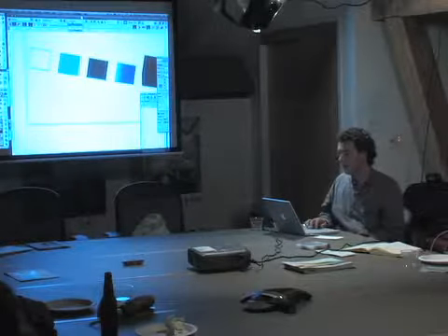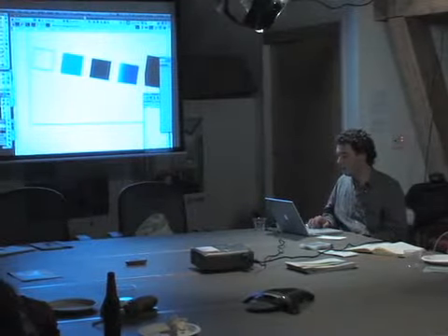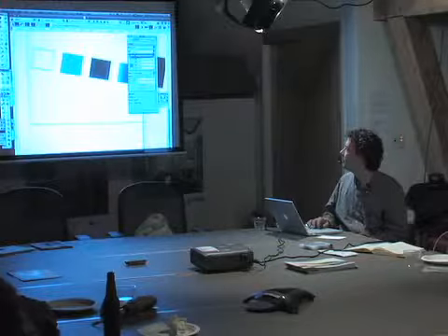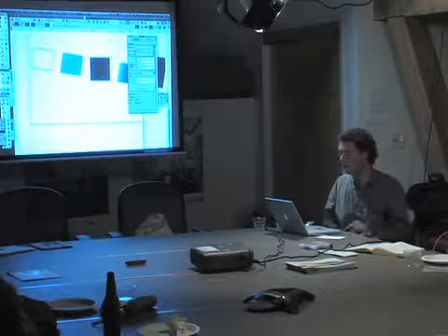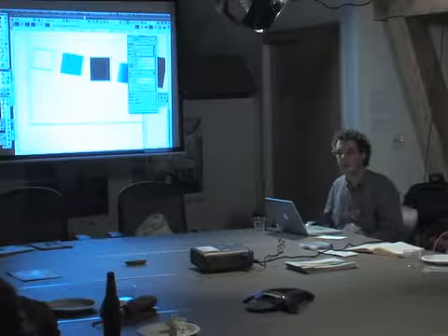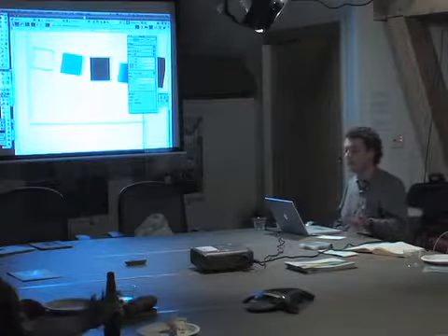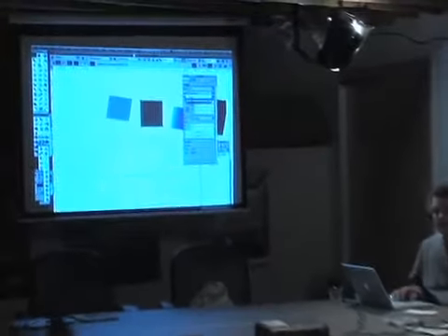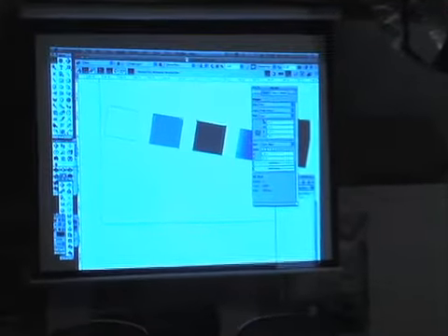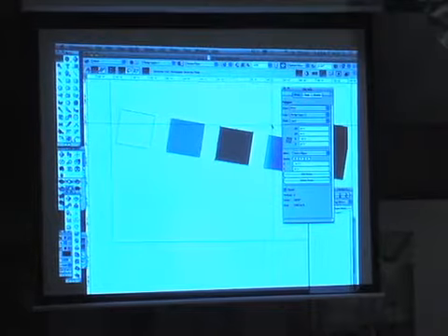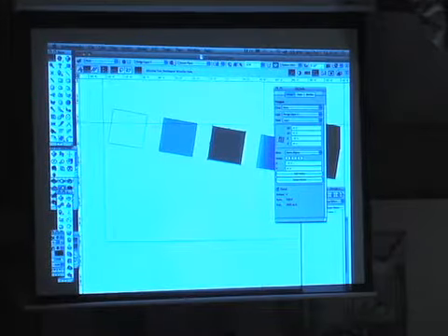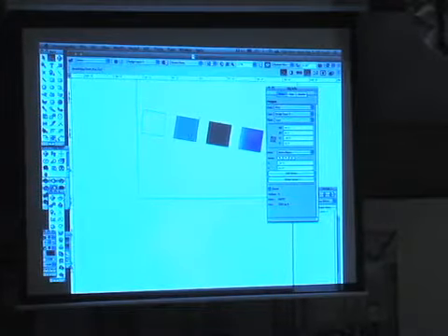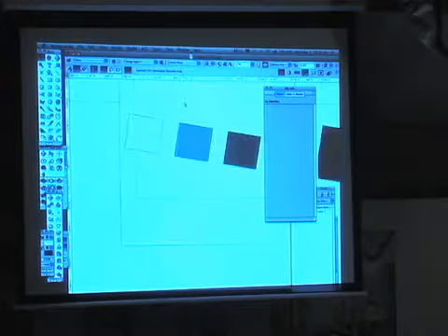Yeah, well, they introduced the layer plane and screen plane. If you take this object, it's now set to show up on the layer plane. If I flip it to screen plane, this is the way it used to work. That's when you had 2D objects and you tried to flip something up into 3D. It would always stay in your face, oriented to the screen. So now you can take 2D objects and apply them to the layer plane, and they'll reorient to the design layer orientation.